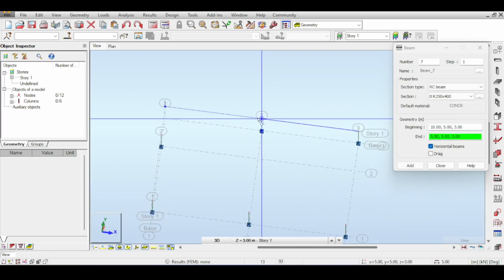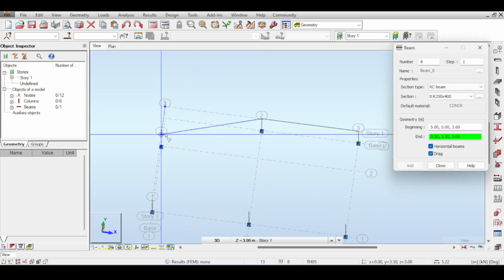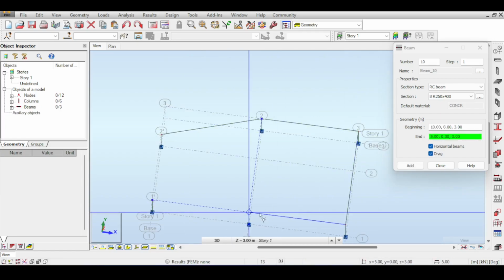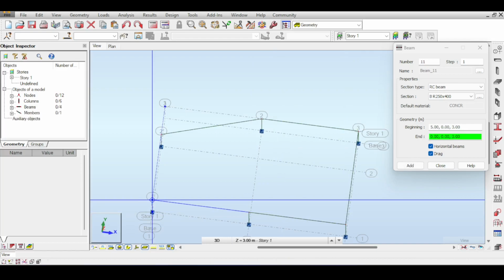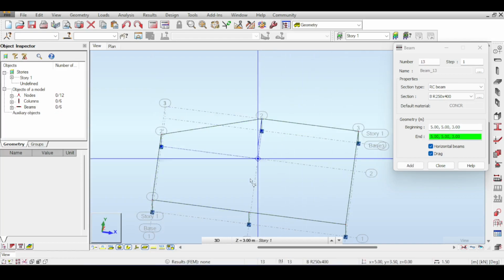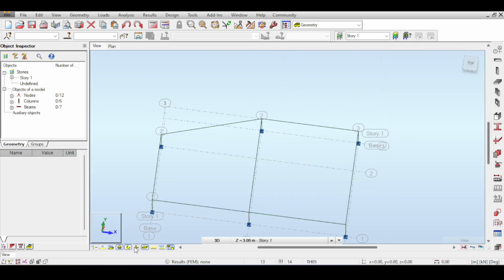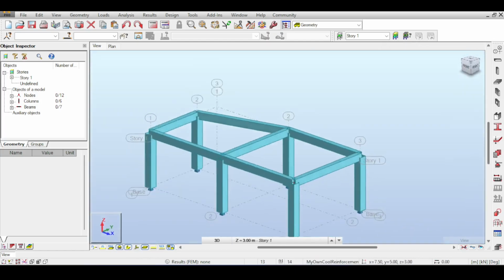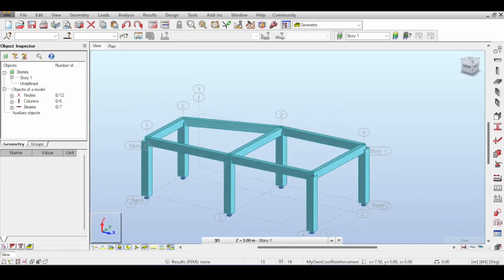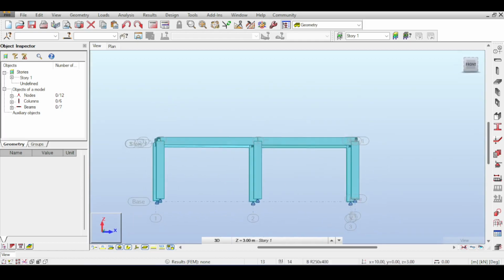There is something called hidden beams, which are beams that are not thicker than the slab. And of course, this is well known around the world. The problem with drop beams, as I'm doing them right now, is that they need finishing, architectural finishing, so that they are not visible to the human eye when they live in the structure. Because if I put a slab now on the drop beam, then the person will see the drop beams, and it would not look really nice. So usually you would have architectural finishing below the drop beam to cover and hide the drop beam.